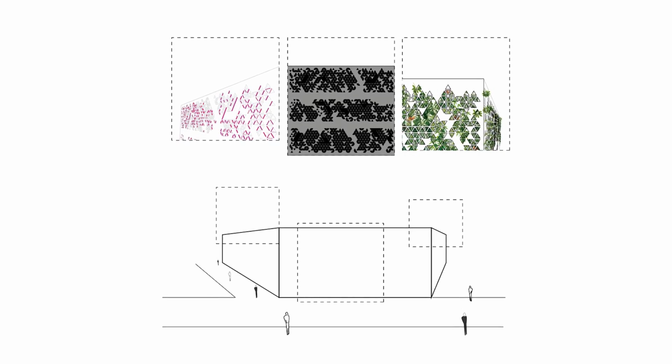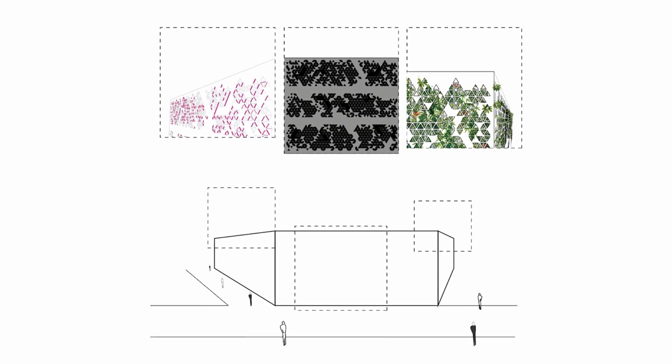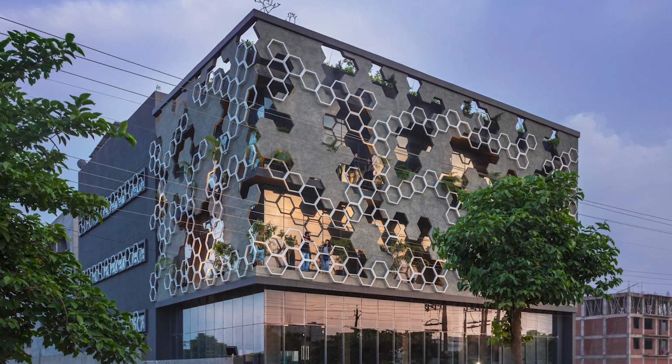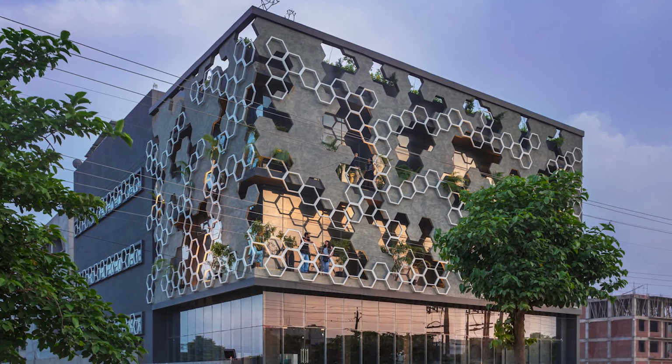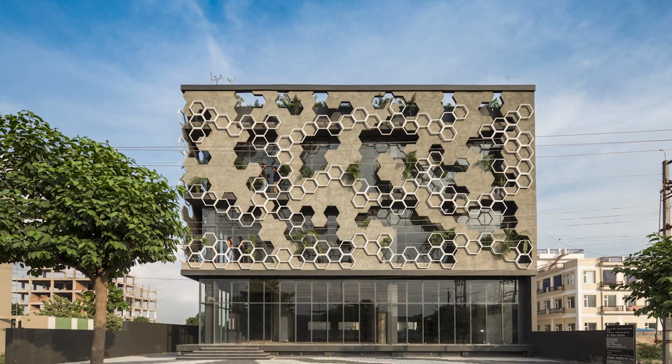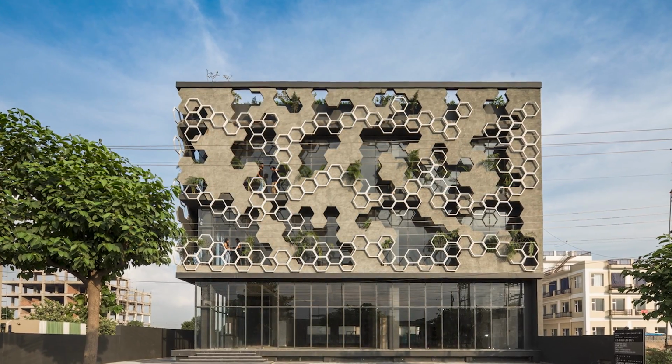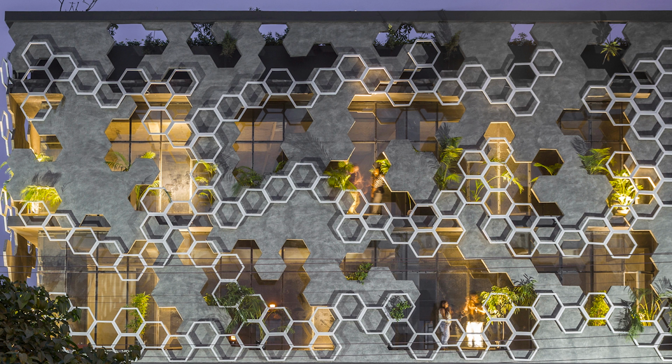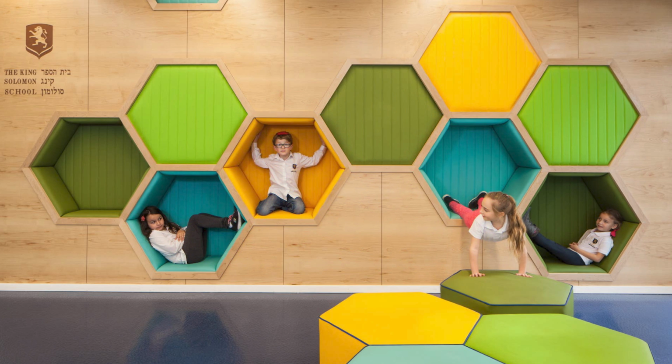Being able to create custom openings in Archicad walls has been a nightmare for a long time, and that's because, of course, we have had no tools for this. Previously you had to use a morph and make it intersect the wall, then use solid element operation to subtract from it and then hide the morph itself in order to have an opening, which would of course take a lot of time.